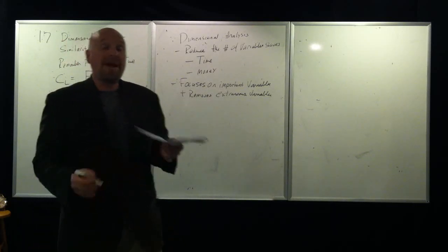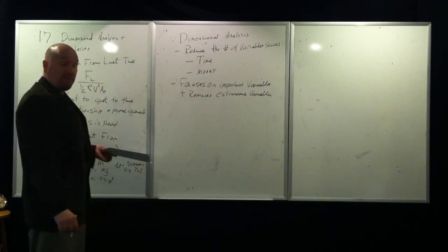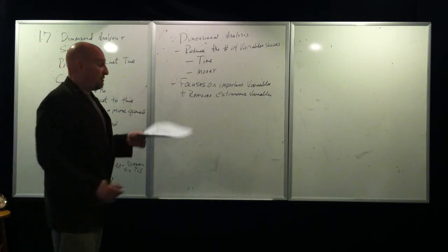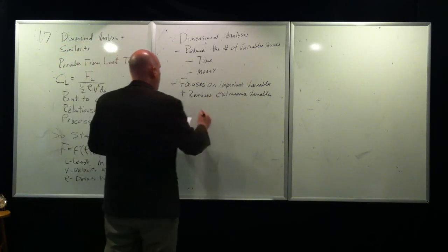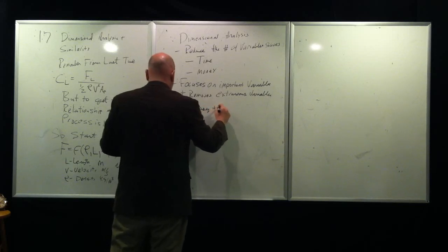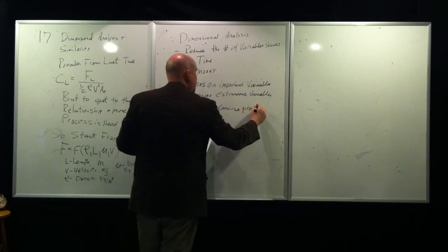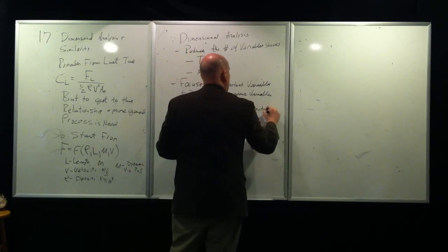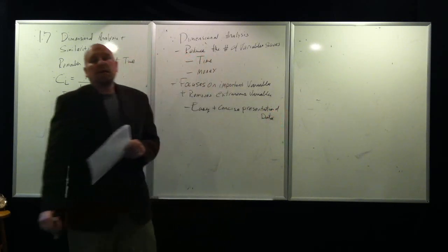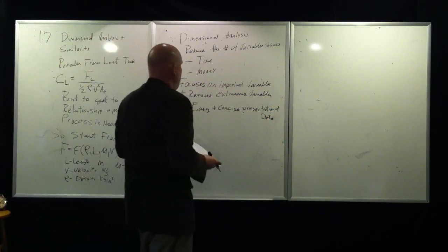You can go through the mathematics and find that maybe there's a function of a particular variable that you would think would be important, but going through dimensional analysis allows you to remove extraneous variables. What that allows is a very concise, easy way to represent the data.